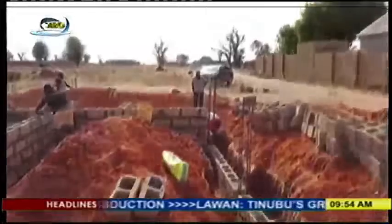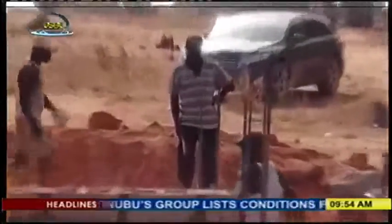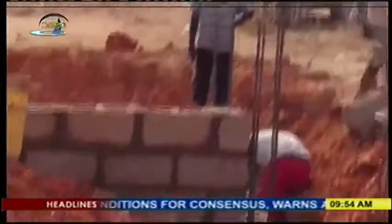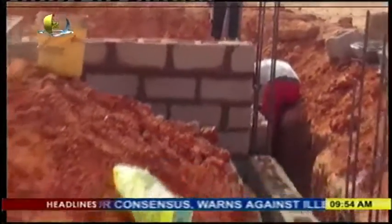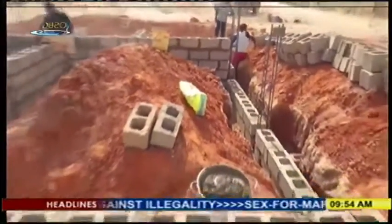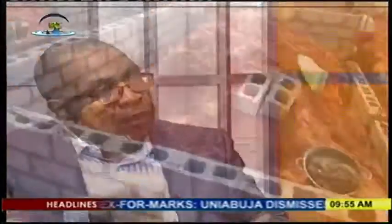In some cases, the structural engineer visits the site to monitor the construction, but it's really not his job to do a continuous inspection. So I believe that we should have in this country a requirement, particularly for very sensitive buildings, where there has to be a qualified testing agency on site to monitor the placement of the reinforcing steel, to monitor the concrete mix, and how it's produced and how it's placed, and how it's compacted, even how you cure the concrete matters.